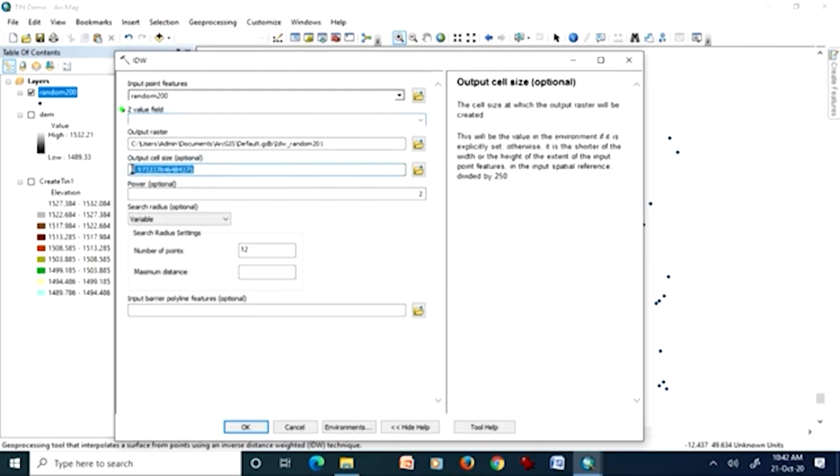And here is the point which I wanted to discuss, the resolution. When we ourselves are creating a surface, we have full control over the resolution. But that does not mean that I have just a few points and I create a digital elevation model at 1 meter resolution. It will not be a very good result. If I want a very high spatial resolution digital elevation model, and the resolution I can control through software, I need a high density of observation points.